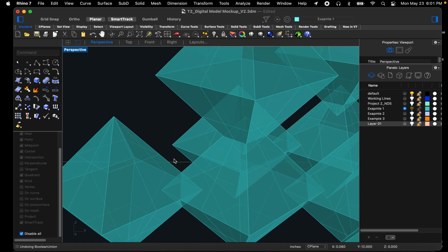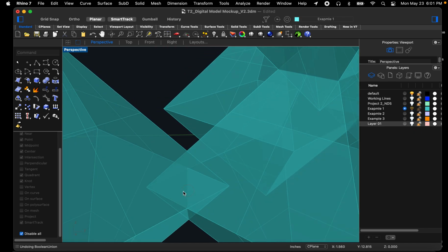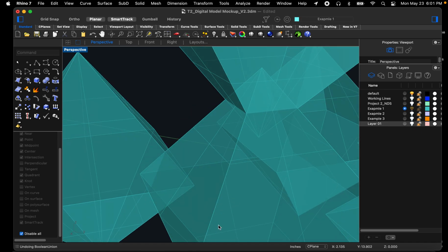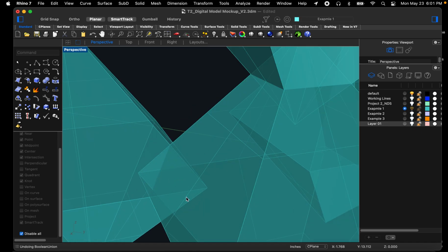Now, if you want these two parts to be 3D printed where they're actually attached, the fact that the software sees this as not inside is problematic. Another potential issue is certain softwares will read this as double density. Okay, you're putting out a certain amount of material here, you're putting out a certain amount of material here. In this overlapping area, it puts out double the amount.